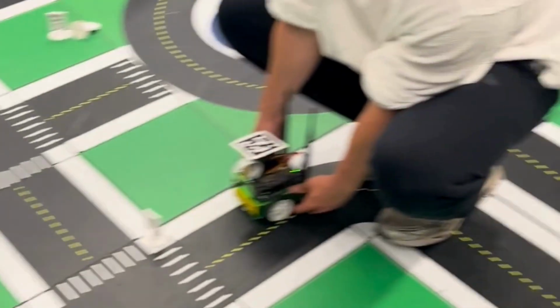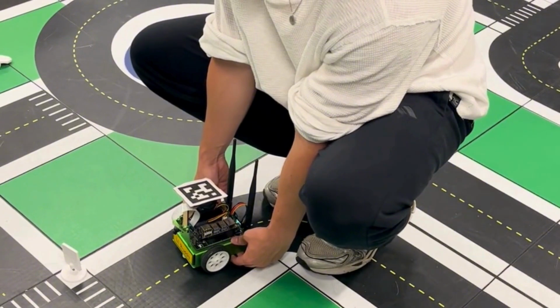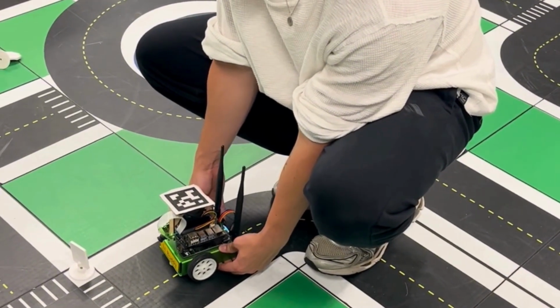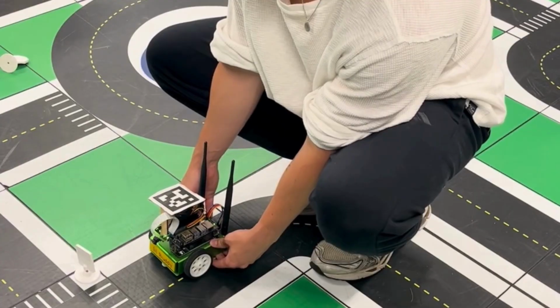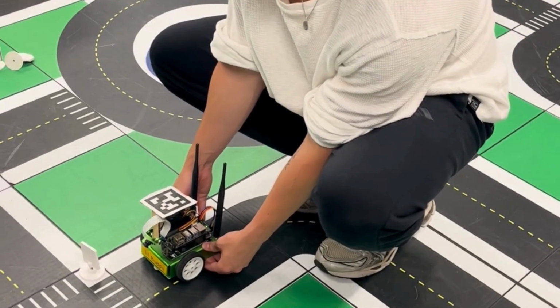As the robot continues onward, our neural network takes note of its surroundings. We trained our model for 10 epochs using 30 images per category, which were a stop sign, turning, speed limit, and a clear road. When the model detects the stop sign with a high probability, it overrides the motor commands and halts the robot safely. After this process completes, the robot continues onward until the next sign is detected.